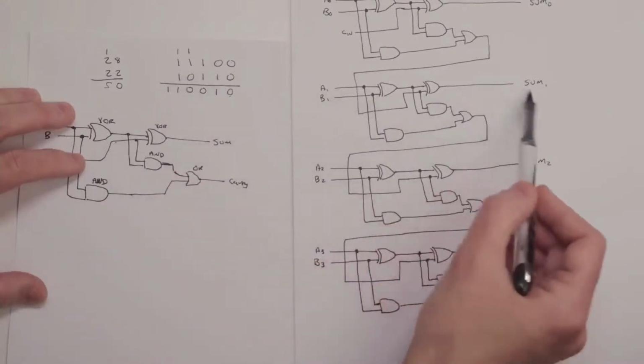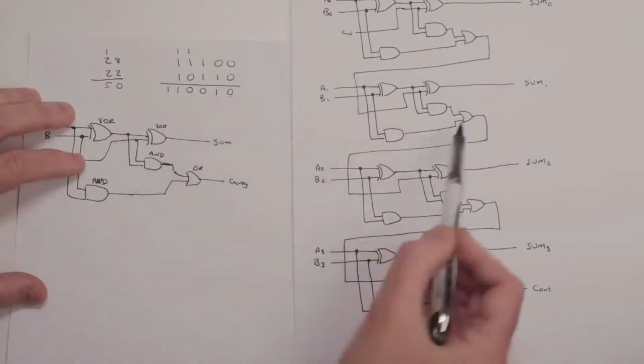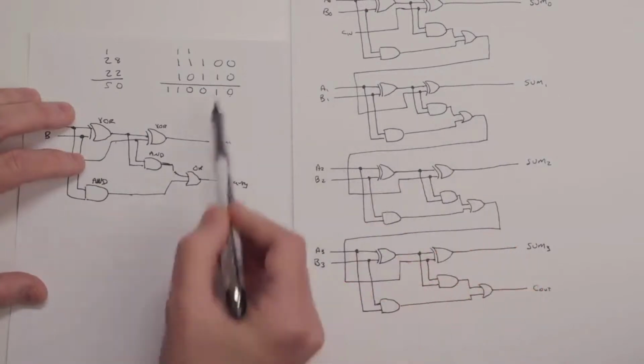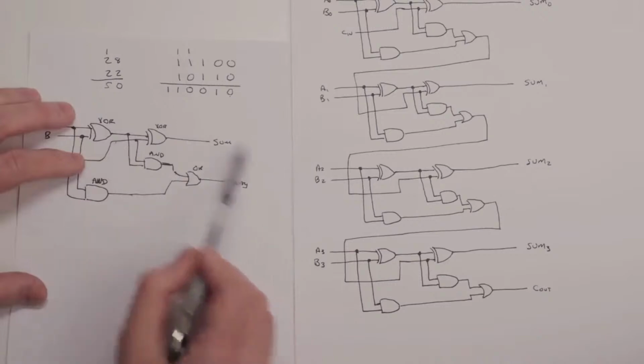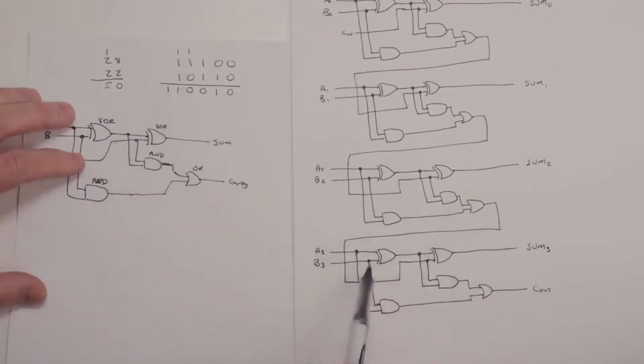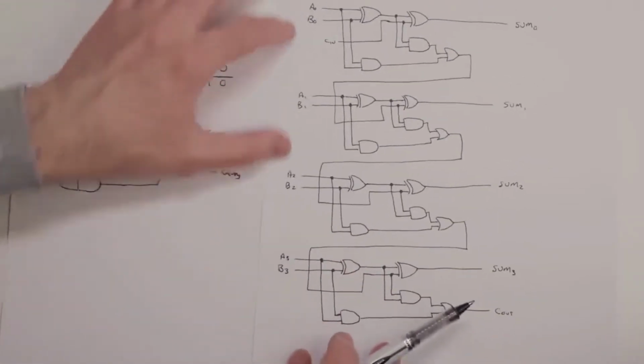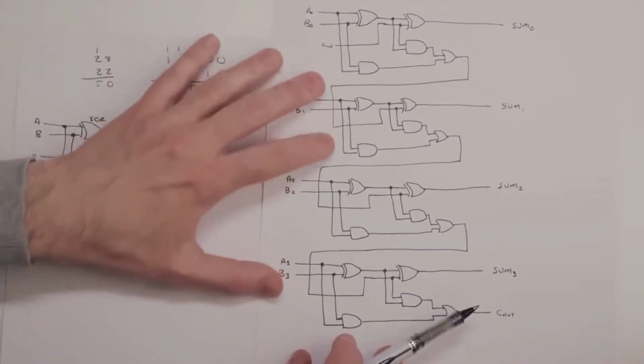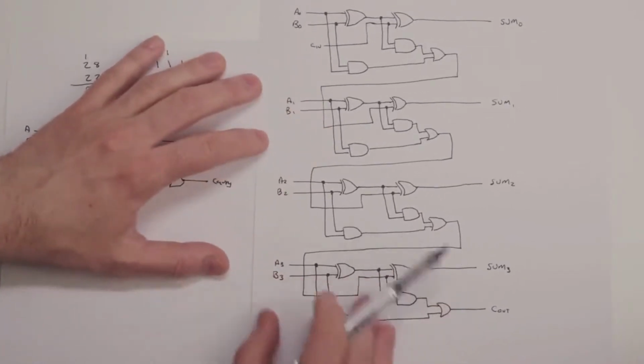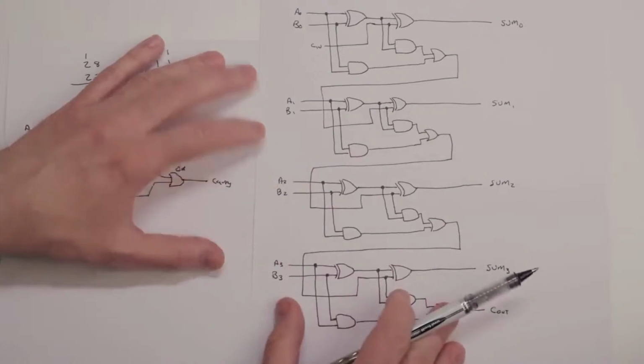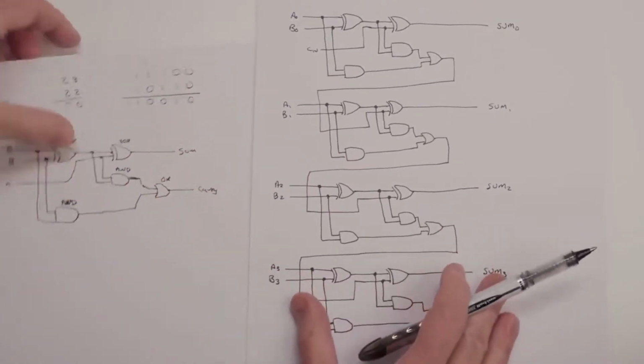And then you have a sum coming out, which would be the number down here. And then you have that carry going over, which goes into the next column, plus the new A and the B for that column. Carry comes out, and so forth. Here I've drawn 4 of them, so we can add two 4-bit numbers, but we could keep building more and more of these if we wanted to. So to actually build this,